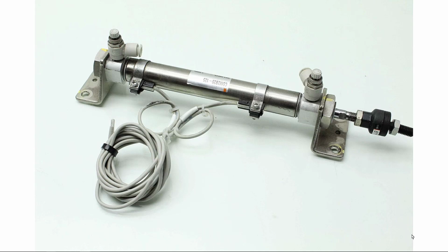Now in some cases you'll have processes where the cylinder is so short, the stroke is so short, that you can't get the sensors in the right position, meaning that they run into each other. And I've had that happen. In that case, what you get is just one sensor, and typically you detect the retracted position, not the extended.